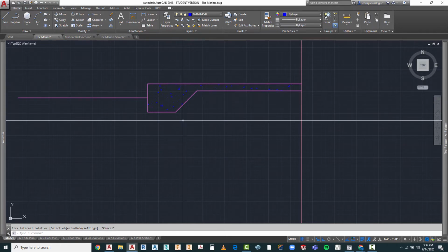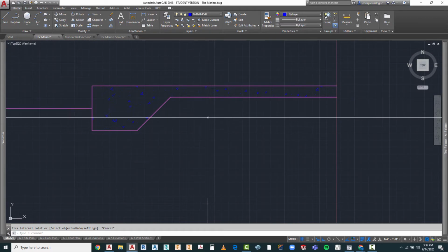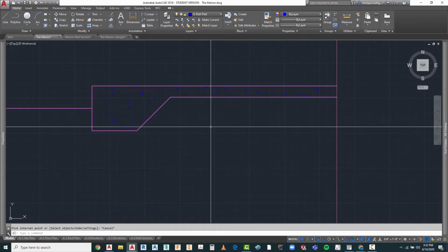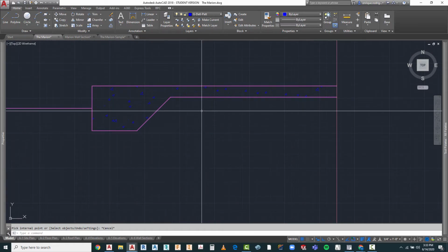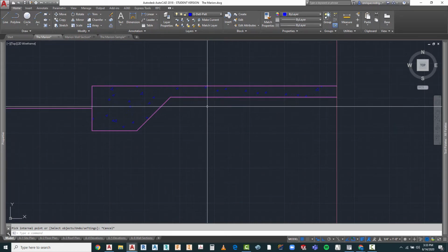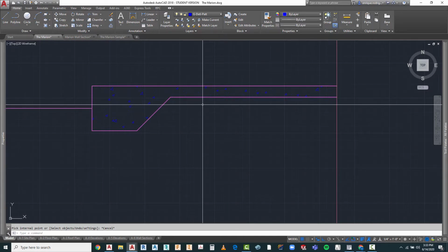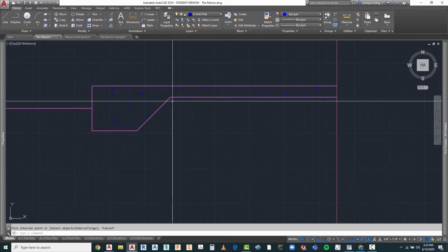So there's a couple of items that we're going to do down below here. One of them is, once we compact the soil, we also termite treated it. In a lot of cases, we'll go ahead and we'll put a 4-inch gravel base, also well compacted to the correct compaction. And on top of that, we put what we call a vapor barrier.